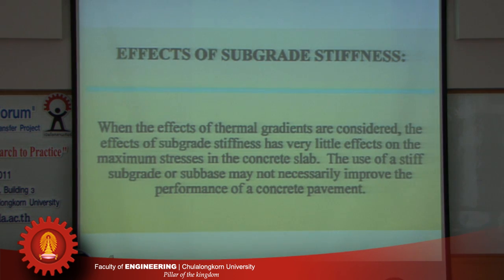So this is the conclusion. When the effect of thermal gradients is considered, the effect of subgrade stiffness has very little effect on the maximum stresses in the concrete slab. The use of a stiff subgrade or subbase may not necessarily improve the performance of a concrete pavement.